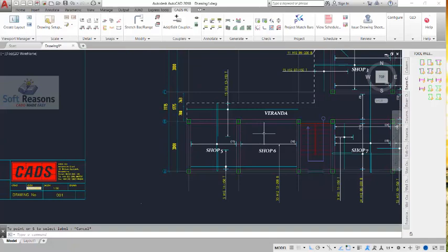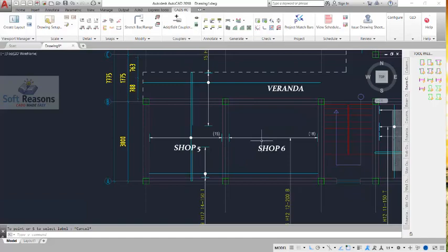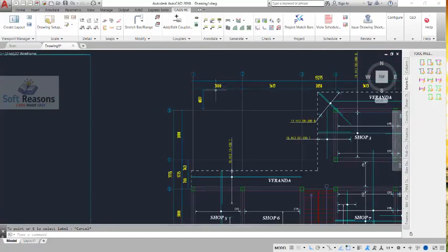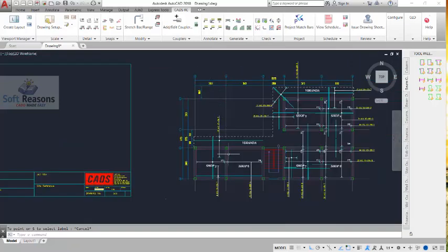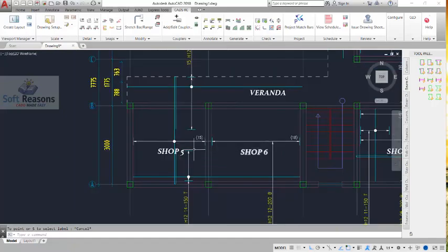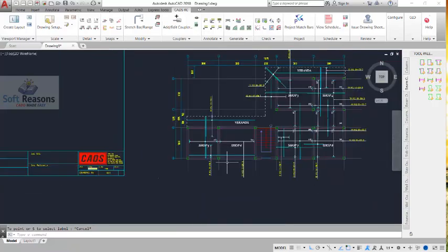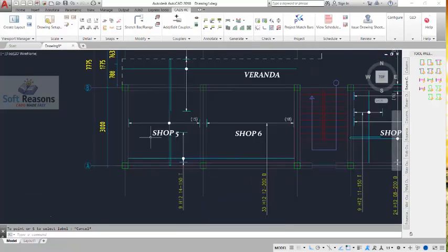All right, so in these other directions, we are to be having reinforcement as well. If you check very well, over here we have 3 meters and we have 3.63 meters. All right, so you have altogether 6.6 meters approximately, which is panel shop 5 and panel shop 6. Okay, it is 6.6 approximately, and the total length of the reinforcement is 12 meters. Okay, so we can run a single reinforcement all across these provisions successfully.